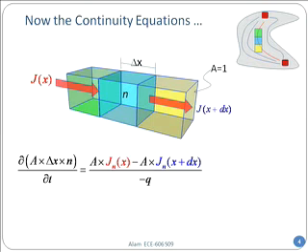Now, how does it relate to the current? Well, that depends on whether the number is growing or coming down, depends on how many are coming in and how many are getting out. Just like in this room, let's say students are constantly flowing in and some of them are leaving. So the number growth within the room will depend on the flux of electrons coming in and the flux of electrons getting out. Now I have divided with minus q in the denominator because these are electrons and I want the number. And so in the J sub n, there is already a minus q. Remember that this is because it's the electron current density.